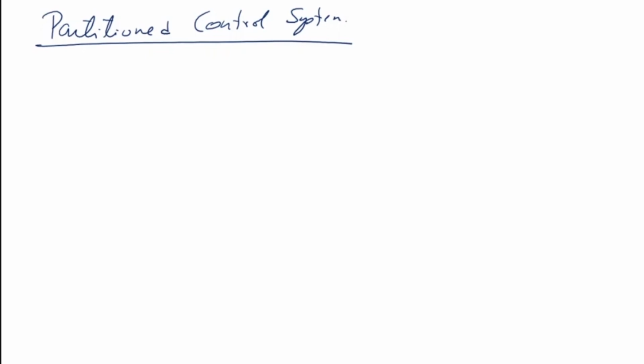So what we basically do is we take the spring mass damper system. Let us make the assumption that we have m x double dot plus b x dot plus k x cubed equal to 0. So we have a nonlinear term coming in here, k x cubed. Now how do we take care of it?